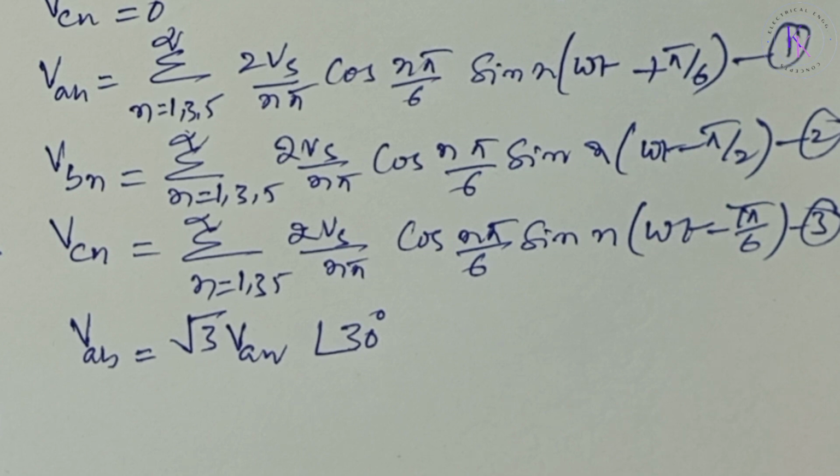Since one transistor conducts for 120 degrees, the transistors are less utilized as compared to the 180 degrees conduction for the same load condition. This is regarding the 120 degrees conduction mode of operation of the three-phase inverter.